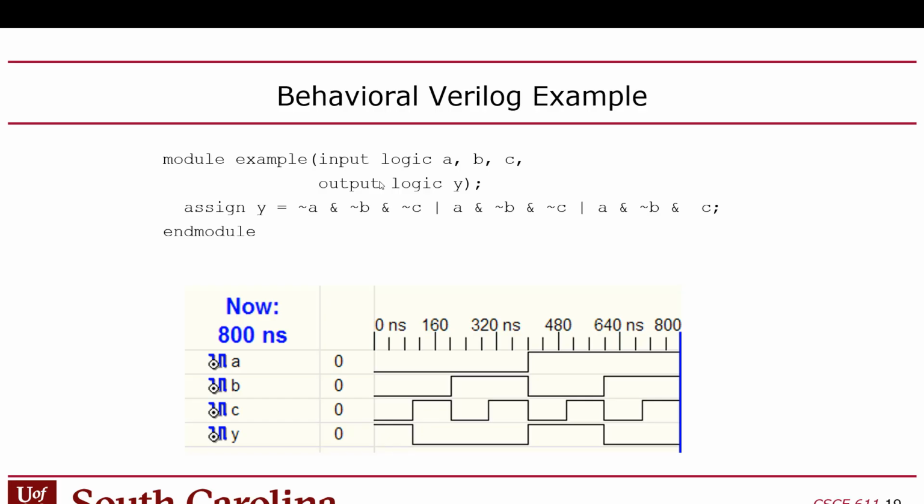On the timing diagram, you don't see it though, right? But it exists because in the simulation, if you change the values of A, B, and C, but you don't advance the time of the simulator at all, like you don't run the simulator, then you won't see a change in Y. But if you run the simulator for any amount of time, then you will see the corresponding change of Y. That's this epsilon time delay.